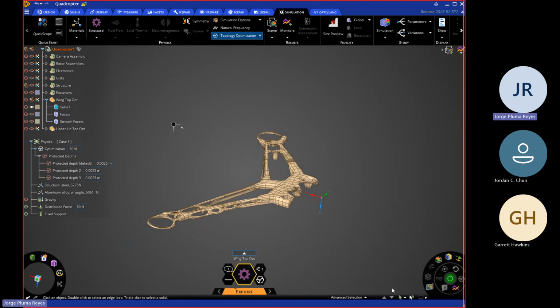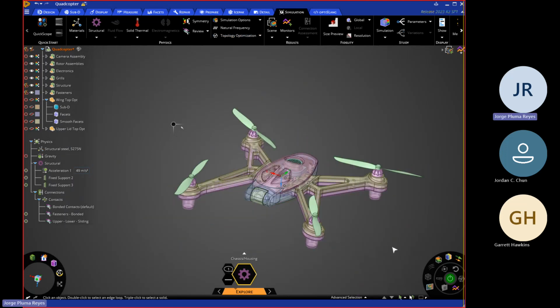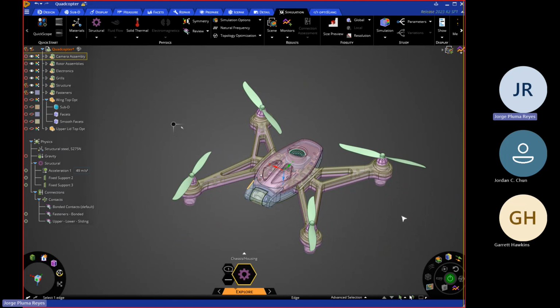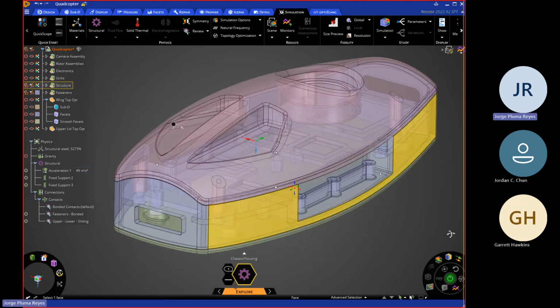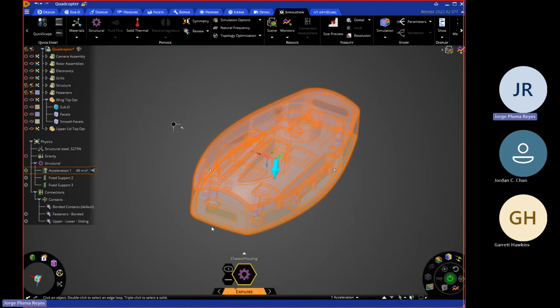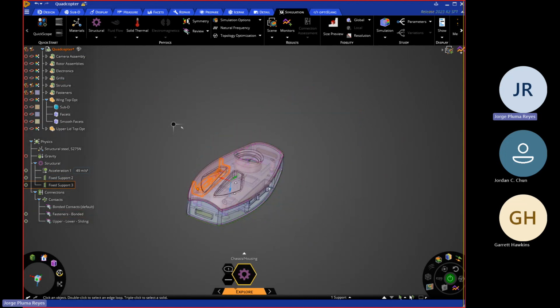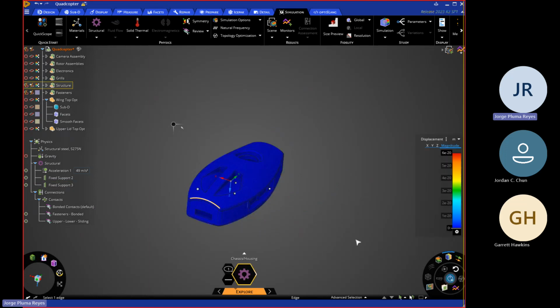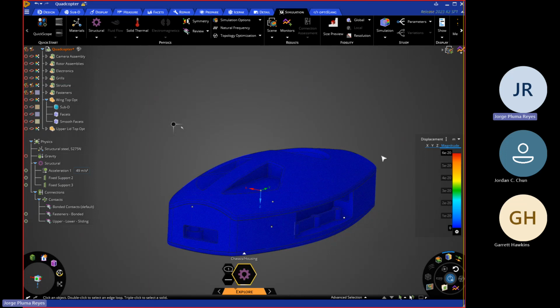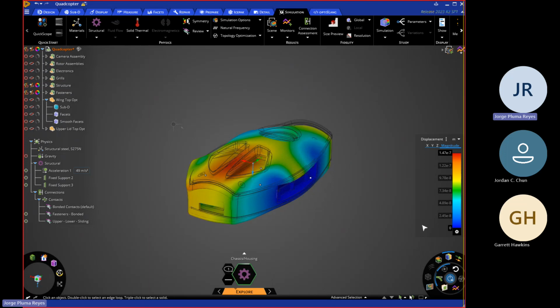But yeah, that was this problem, and I'll give a quick example of what's something you guys will be doing, which is the chassis. So let me go ahead and hide all suppressed. And this is that center body, right? So here, similarly, I put some gravitational loads. I fixed my locations where the wings would go, and I'm letting this body kind of just go up and down. And I modified my contacts. And I think, again, this is the part where you guys probably will be working with something more in this realm here. And here I can see my results again, right?